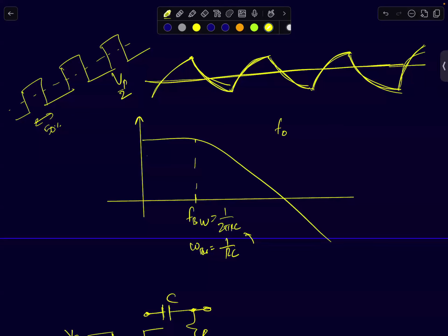If you remove the DC component out, you can always find within one single period one point around which the function will exhibit odd symmetry. Meaning it will obey this property, f of t equals minus of f of minus t. If you cut this waveform in one unit interval, one time period, you can always find some point around which the function will exhibit odd symmetry. If it does that, then you know the function can only contain odd harmonics. It's a purely odd function. Therefore, it will only contain odd harmonics.